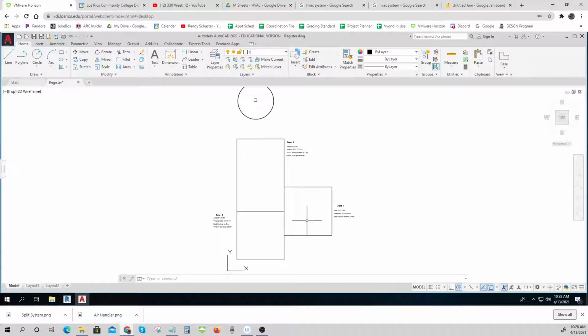And so if it says that you need a peak of, say, 900, and you go, well, I need 6 of these registers or 8 of these registers, and it doesn't really match out, it's okay. It's okay if you push in too much air. It's better too much than not enough. But if you double or triple the amount of air that you're putting in here, that's just overboard. That's too much. Okay, so it's a balancing act.